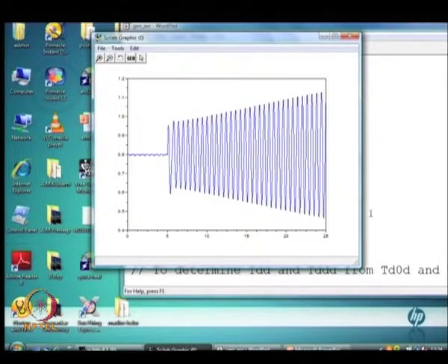Now, why do I call it small signal instability? The point is that this kind of behavior is evoked even if I make the disturbance very, very small. So, it is a problem with the equilibrium point. If you do a linearized analysis around this particular equilibrium point, the eigenvalues of the linearized state matrix would turn out to have an eigenvalue with a positive real part. So, this is what essentially you are seeing here.